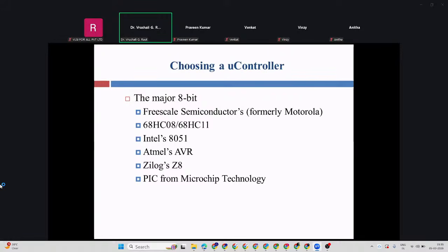Okay, now, as we have started, we are studying 8-bit microcontrollers. And what do you mean by an 8-bit microcontroller? At a time, your microcontroller can process 8 bits of data. Is it right? That is what is meant by 8-bit. If you have a longer stream of data, what do you have to do? You have to cut it into parts of 8 bits, 8 bits, and so on, and accordingly process it. So we are talking about 8-bit microcontrollers.